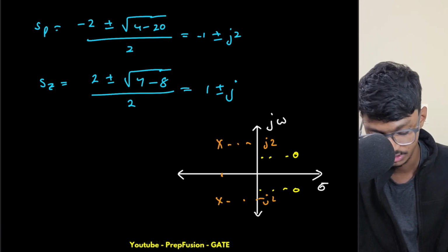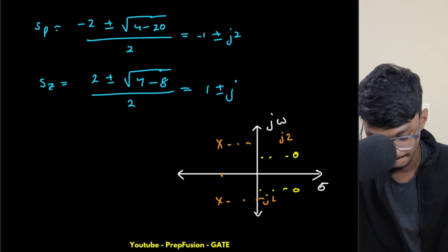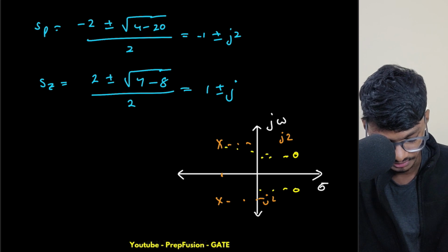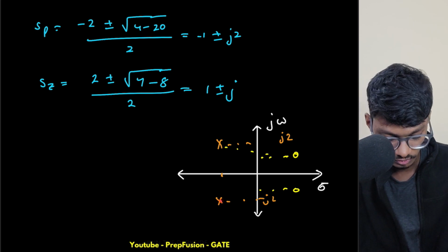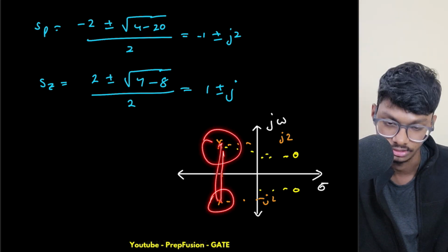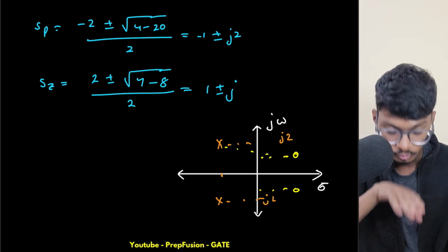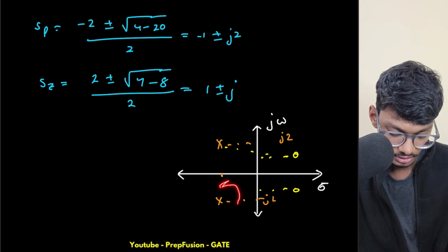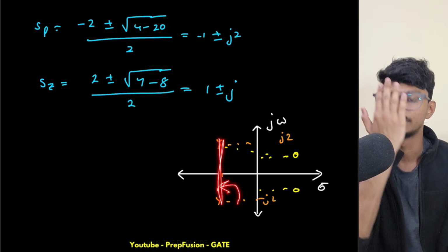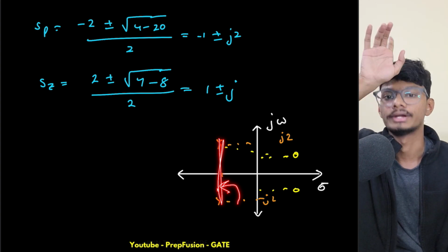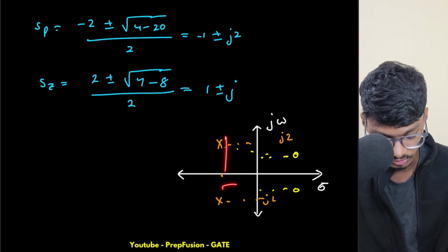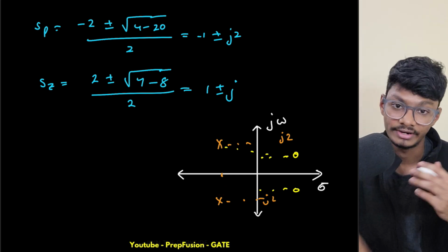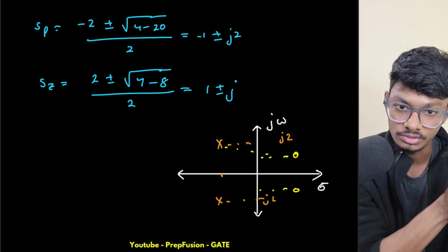So obviously what we do is we find all of the angles contributed due to the other poles and zeros. That is what we find, right? The angle contributed due to this pole is what? I'm looking above in the anti-clockwise direction, moving 90 degrees. This is exactly on top of me, above my head. So this will be plus 90, in the anti-clockwise direction. That's why it is plus. We'll find the individual angle contribution due to the poles and the zeros.